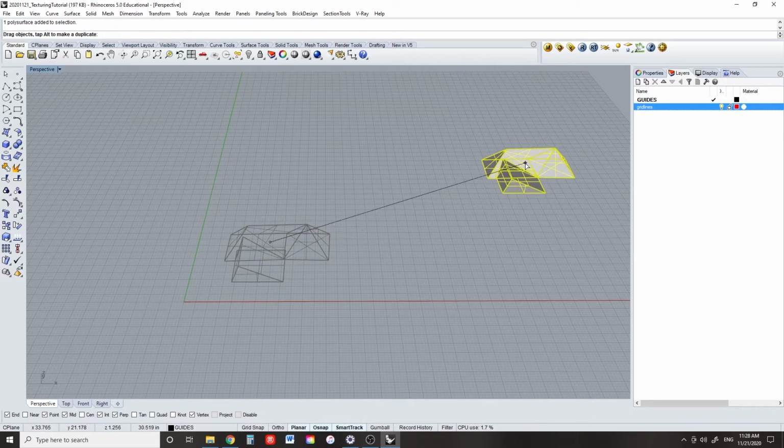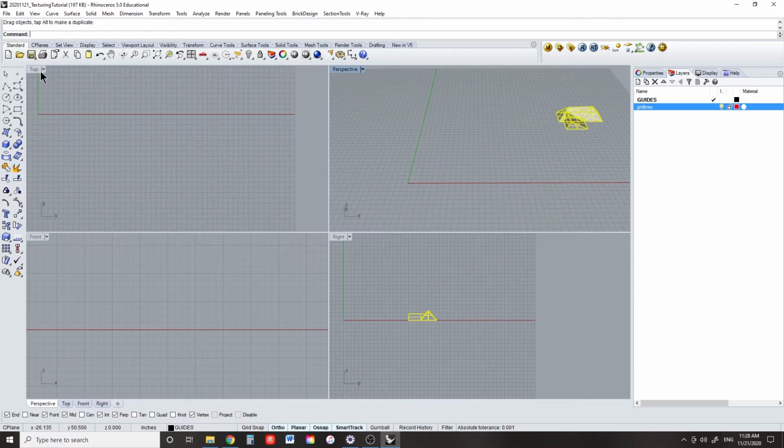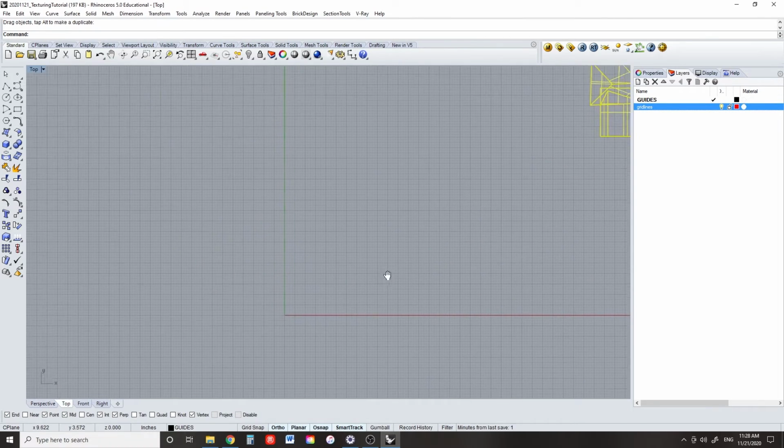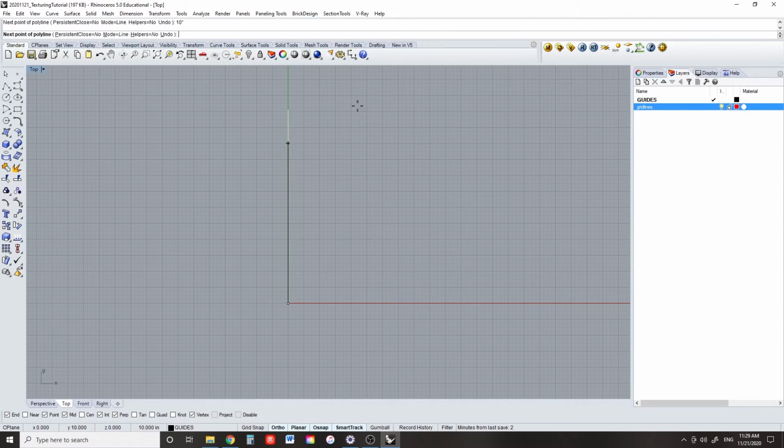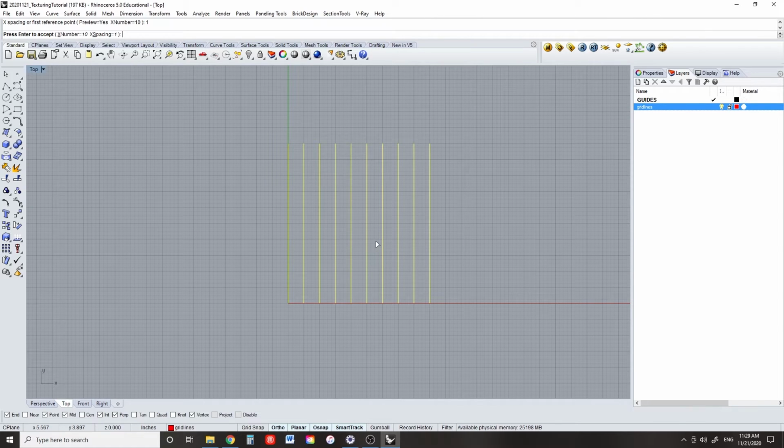The first thing we're going to do is to construct a ground plane out of grid lines. So let's make a grid using the array command. First draw a polyline, and then use array. The array command will allow us to copy one object multiple times in one operation. In this case, let's go in the X direction. So we're going to select how many lines we want in the X direction. Let's type 10. For Y and Z, let them default to 1. And then for spacing, type 1 for 1 inch.